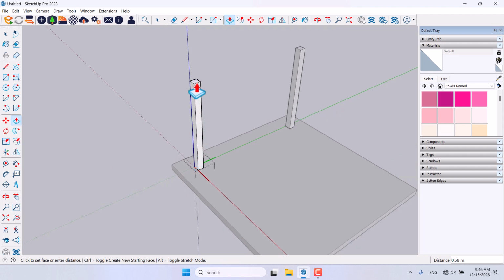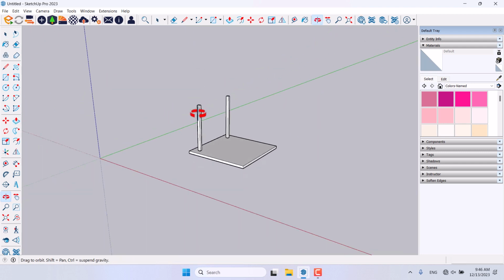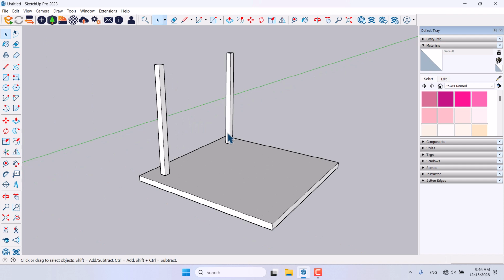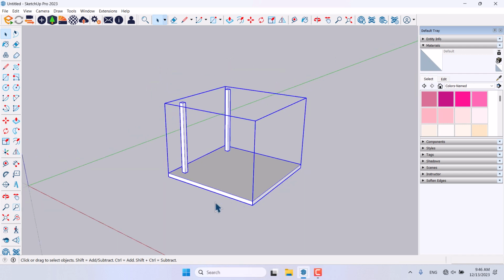So the difference between the component and group is that. So I'm going to type 0.74, and now I want to show you one of the best new features in SketchUp 2023.1. It's about the flip or mirror option. So I'm going to select all of them and convert them to a group in here. And now you can find the option called flip in the large toolset, or in the getting started toolbar after the scale option, you have the flip option.